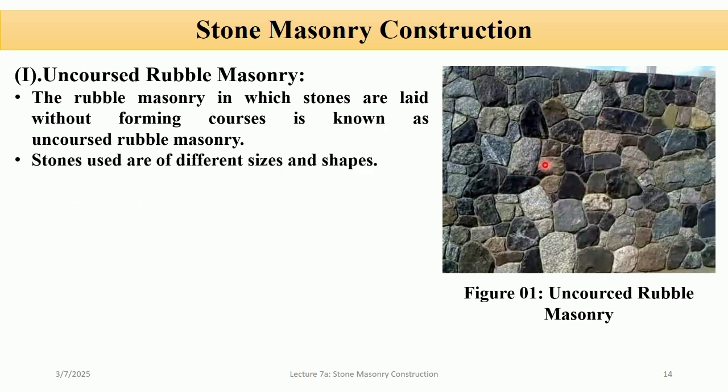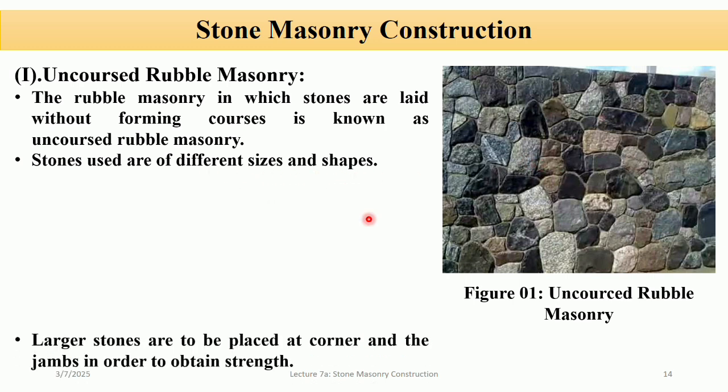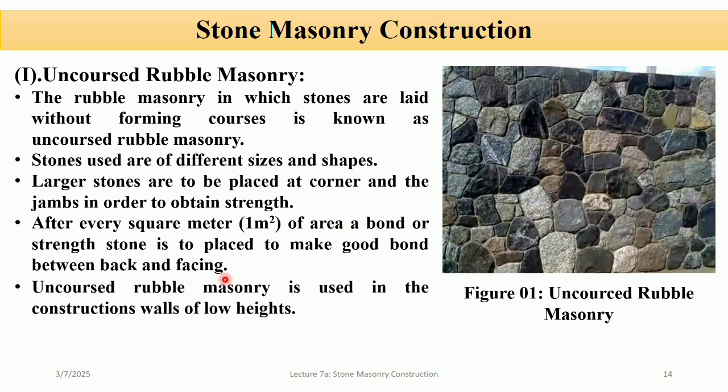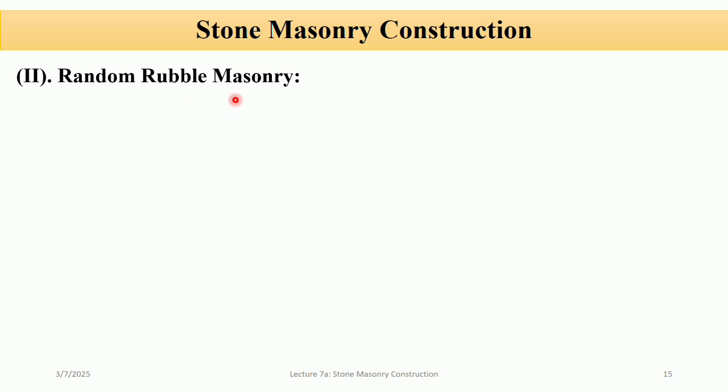In this, the stones which we use are of different sizes and shapes. After every square meter of area, a bond or strength stone is to be placed to make a good bond between backing and facing.